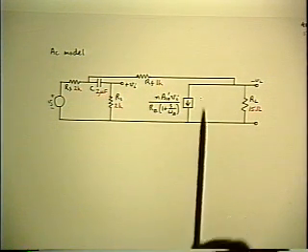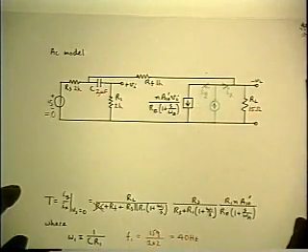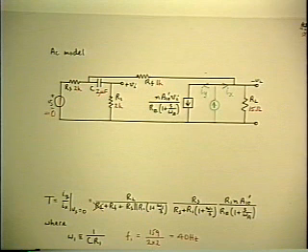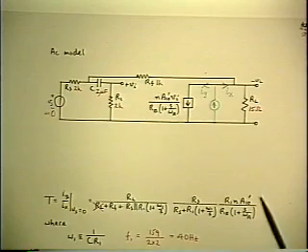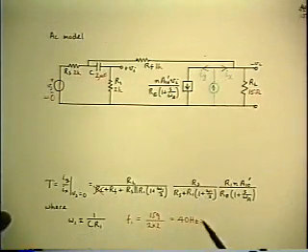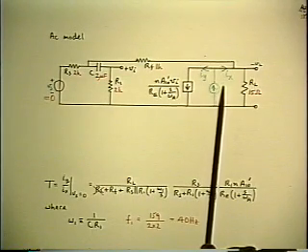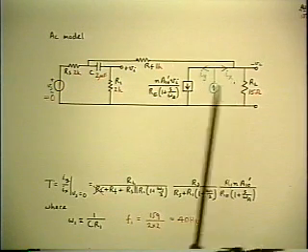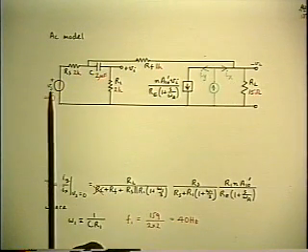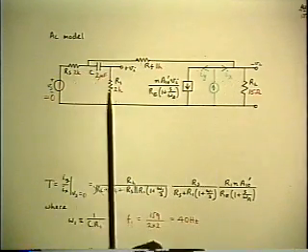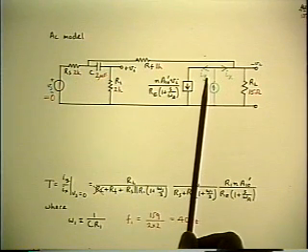So we've decided we're going to choose point Q to do current injection for the purpose of measuring loop gain and for the purpose of measuring G infinity by using null double injection, which are the two basic parameters we need to solve the problem. So let's do loop gain first. T is IY over IX single injection when the VS is 0. So all you do is follow IX around the loop back to IY.